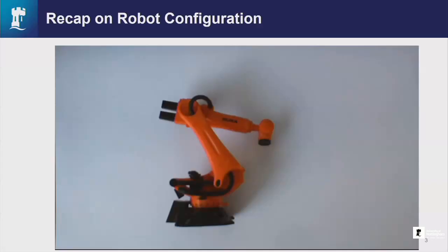And then the next one up, there's a bit of a link here, and the next one up is another revolute joint, but the axis of revolution is out of the board towards you, for example, which allows that arm to rotate around the horizontal axis and move up and down, okay? And then we move to another revolute joint here, whose axis of revolution is again out of the board, and that again allows that link to rotate in the plane of the board. Okay?